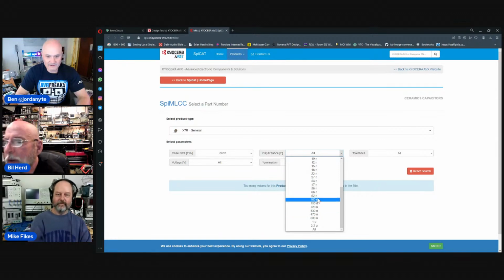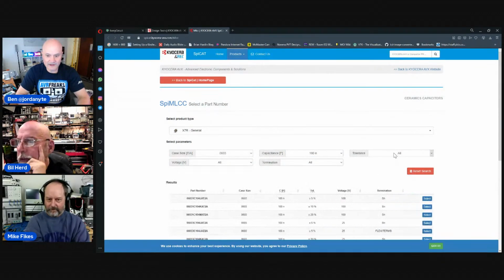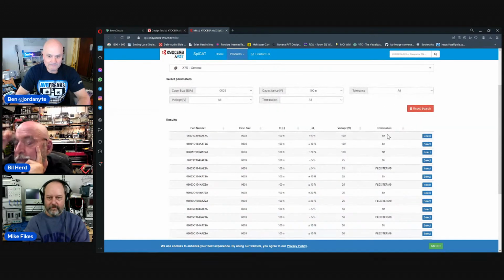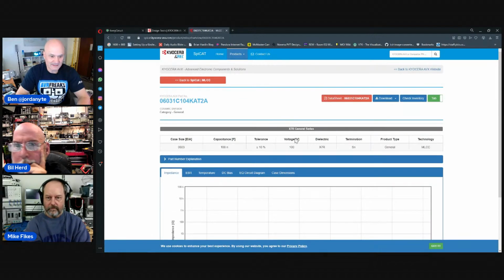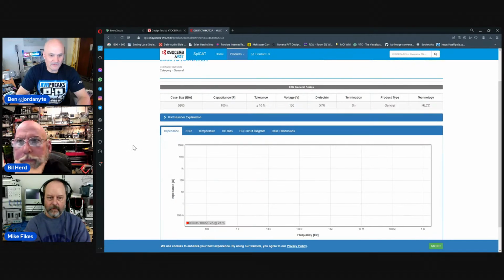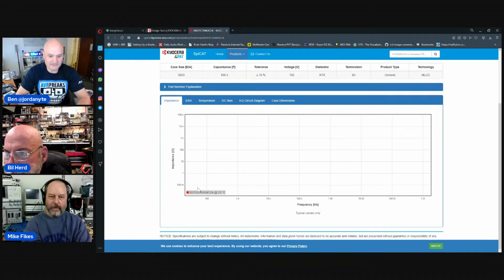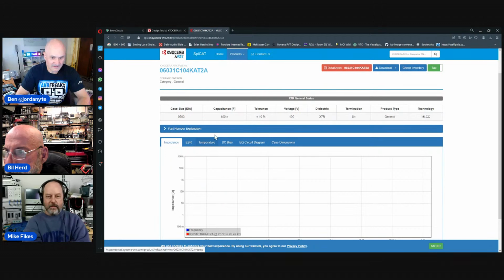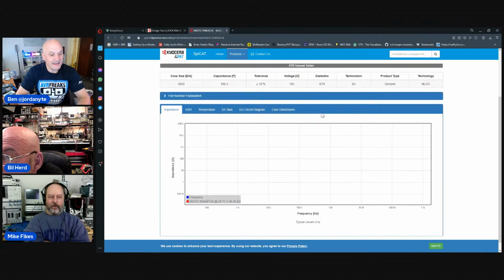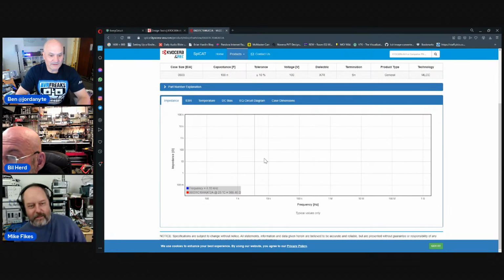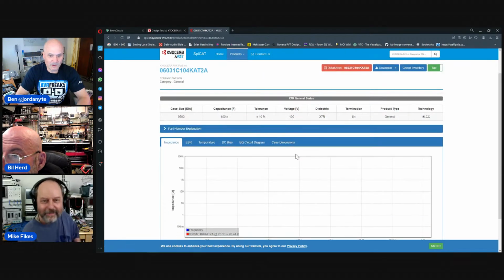And 100 classic, 100 nanofarad. So let's look at this. A typical cap that you'd buy from DigiKey for your project. And look at this, they give you online, they're simulating. Why am I not seeing a graph here? And I noticed in SPICE you can set the temperature. You can set the temperature that your board is running at, or sweep it across. Because these things vary widely.